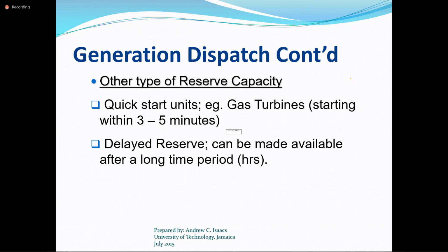Now, the automation I spoke to occurs, for example, and I know I'm touching a little on protection, where you may have a fault on the system, and you have a recloser which, depending on the fault, will seek to reconnect the system.